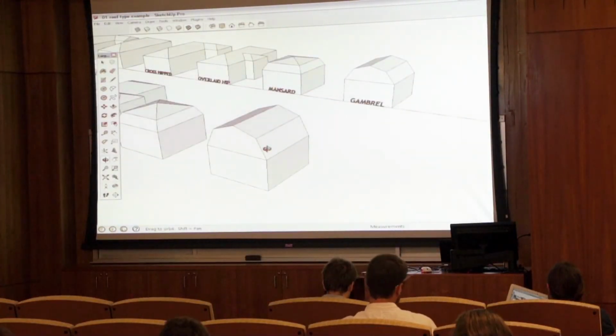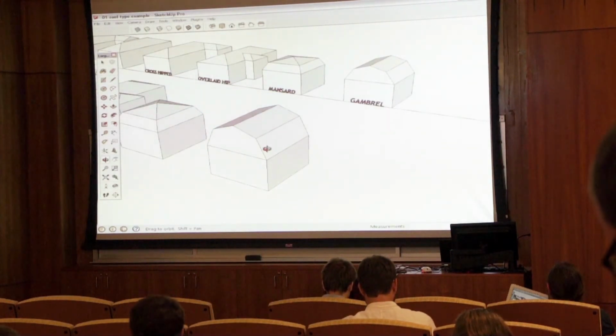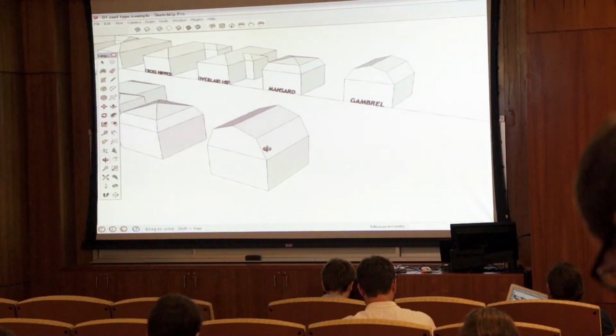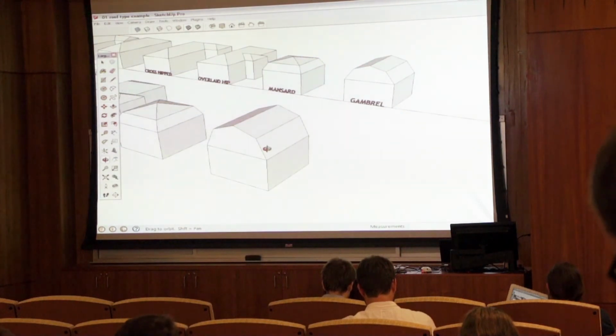So if your faces are reversed, you can take the select tool, right-click on it and select reverse faces. Or if you have a lot like this one, click on a face that's correct and right-click and then select orient faces. Sometimes that orients the mismatched ones correctly.